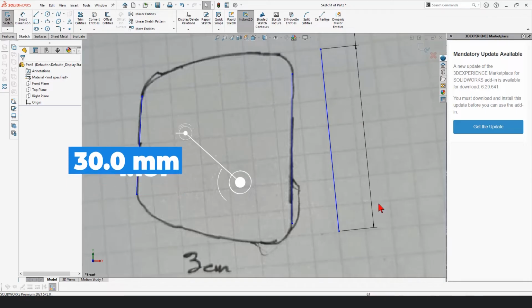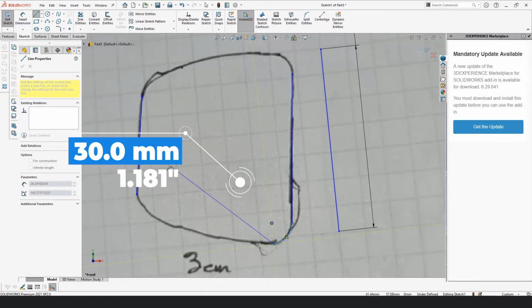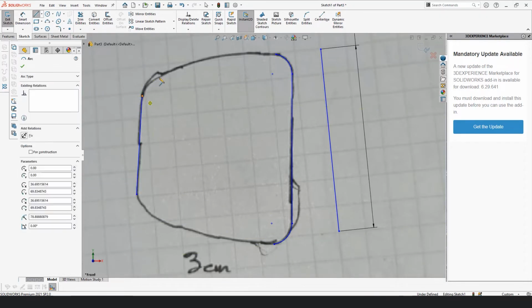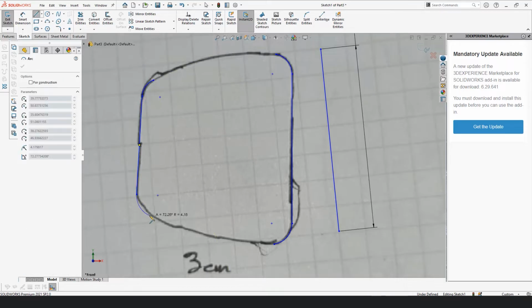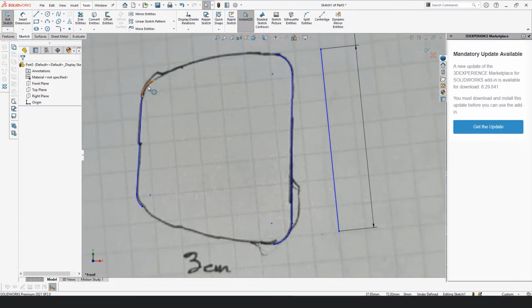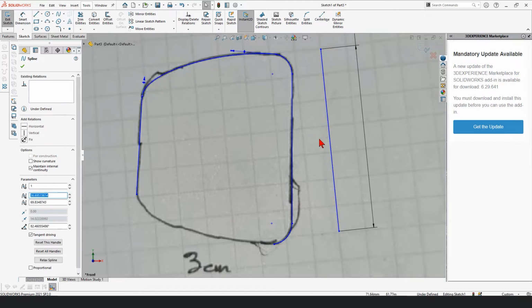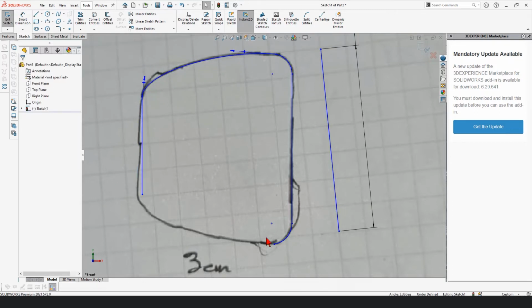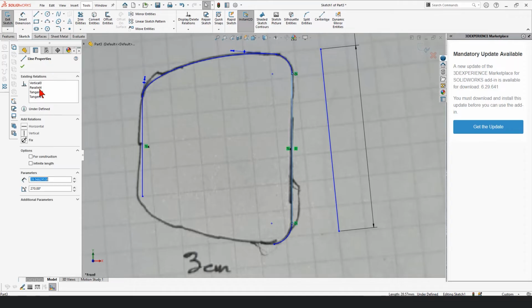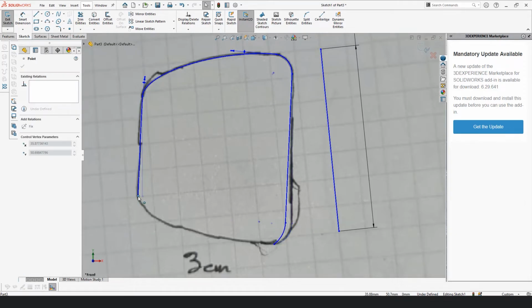So 2 straight lines, and over here we have curves, and I'm gonna go with spline for these 2. We have 4 rounded corners. Different tools can take care of that. We're gonna go with sketch fillet and then round them. Okay? Now, once the sketch is closed, I have the inner sides of the pocket.